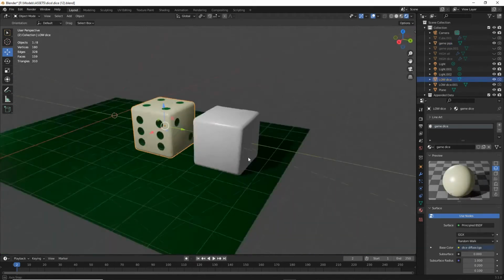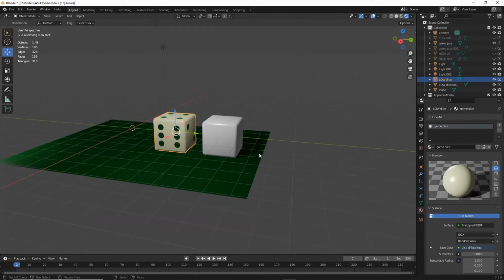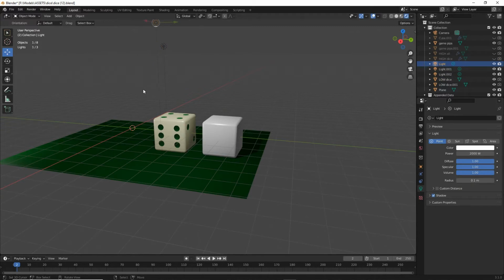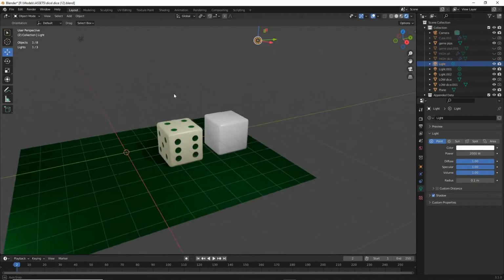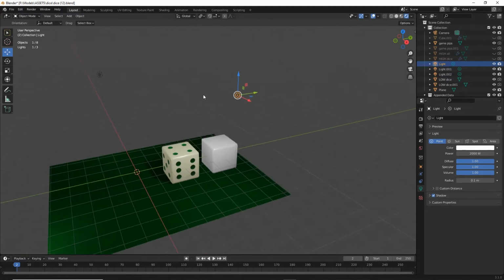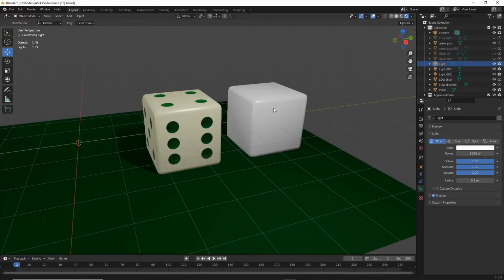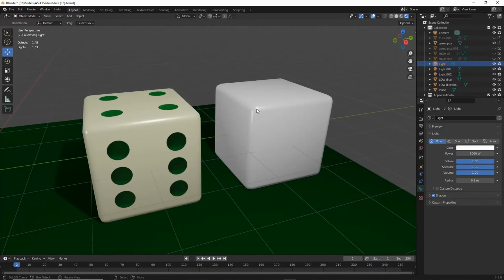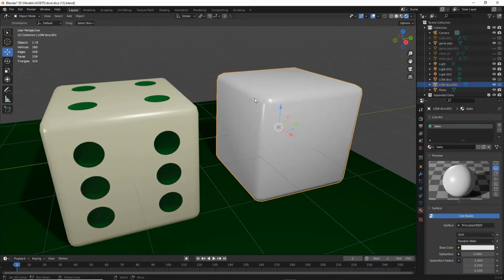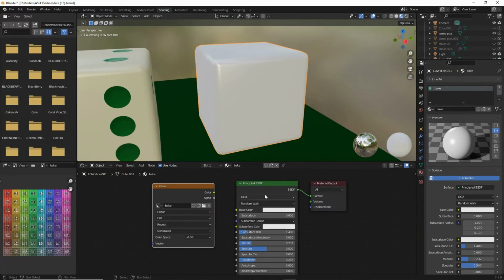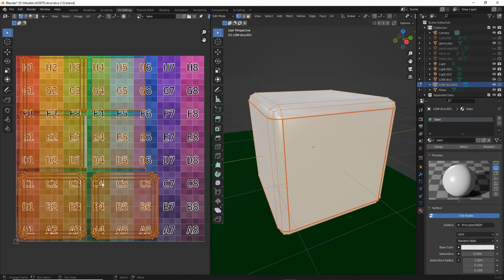To bake textures relative to the scene so they include things like shading and shadows, set up the scene so that we have our lighting and our objects placed relative to where they need to be and the effect that's wanted. Then for the object being baked, make sure it has a material, a basic material, with an image texture node assigned. This does not need to be connected to base color. To this, we need to make sure the object is UV unwrapped and mapped.